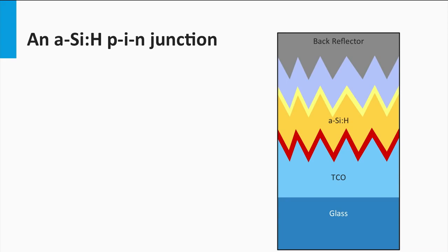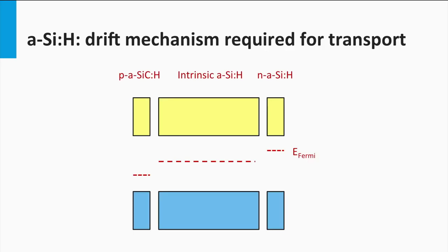The absorber layer is based on an intrinsic amorphous silicon absorber film, which is sandwiched between thin layers of p-doped and n-doped amorphous silicon. The red layer indicates the p-doped amorphous silicon and the yellow indicates the amorphous n layer in this illustration of a single junction amorphous silicon solar cell. The p and n doped layers create a built-in electric field over the intrinsic absorber layer. This can be illustrated by an electronic band diagram of the amorphous silicon solar cell.